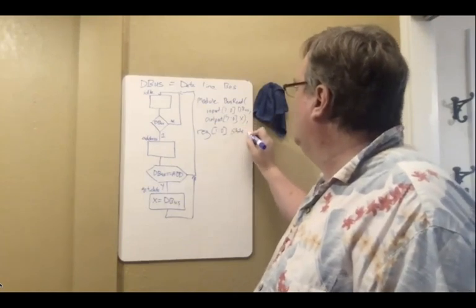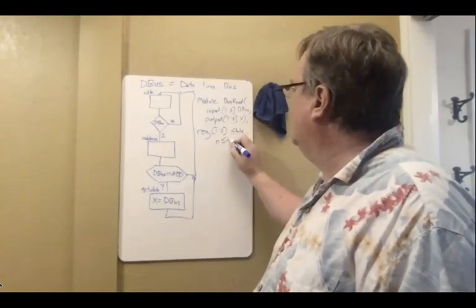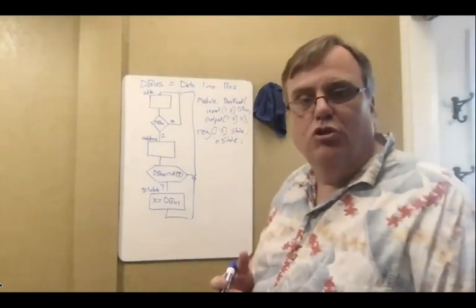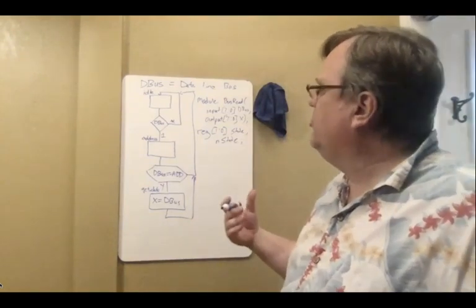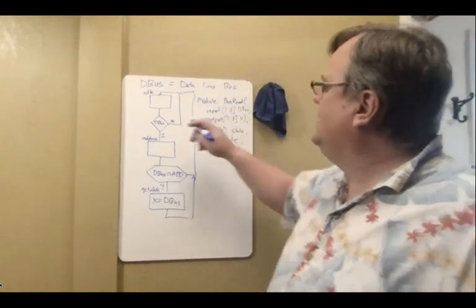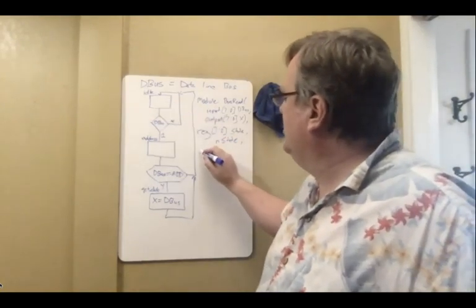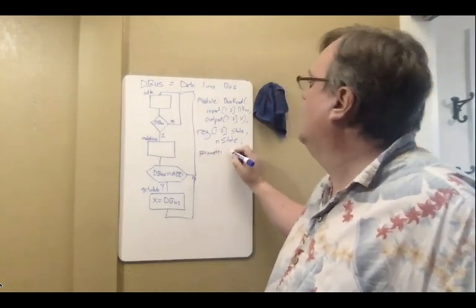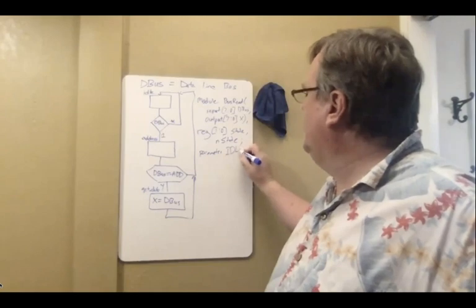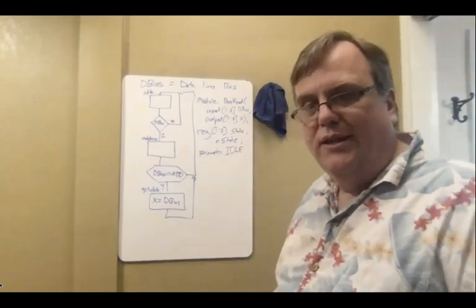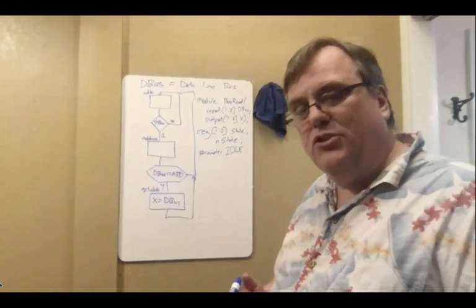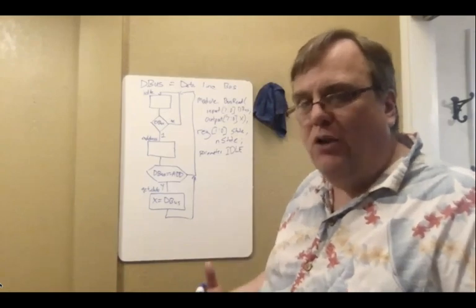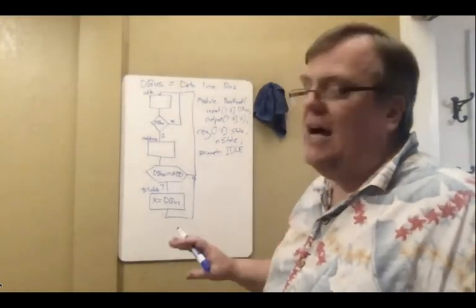State and next state. So I've now got my 2 bits set up for those. I know I want to do them gray code. So to make my life easy, I'm going to actually set my states as parameters. By convention, parameters should be all capitals. So again, convention doesn't mean it's required. Convention means that's what everybody's going to expect, and if you follow that, your code is readable and self-documented.